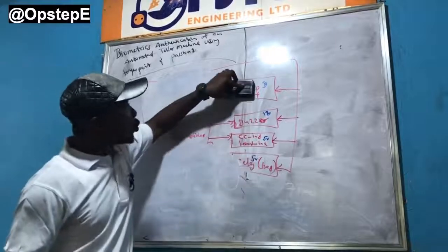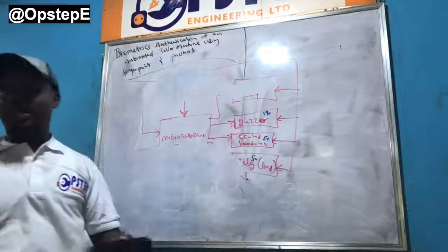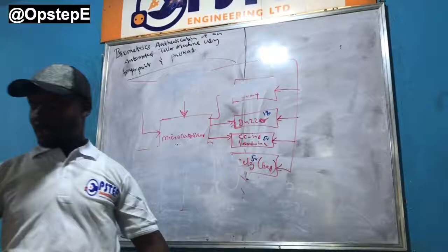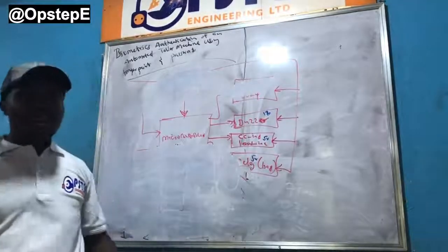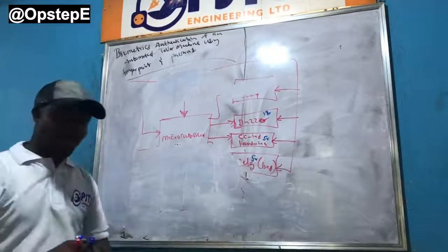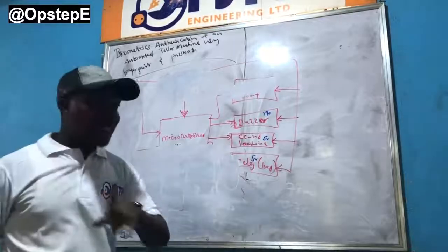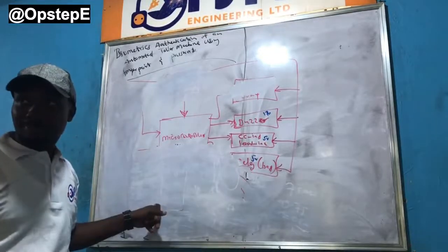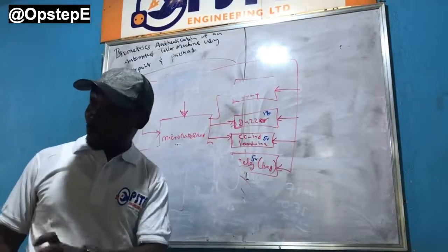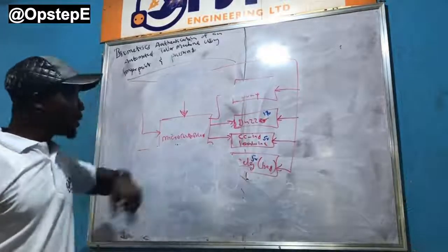Okay, so now again, don't forget, I didn't forget to say that the SSD is a 4-line communication we're using, like the serial, which means your D4 through D8 are all used. And I need to actually tell you something on the SSD. Because the keypad has taken my port B, I'm left with just port A and port C on the controller.